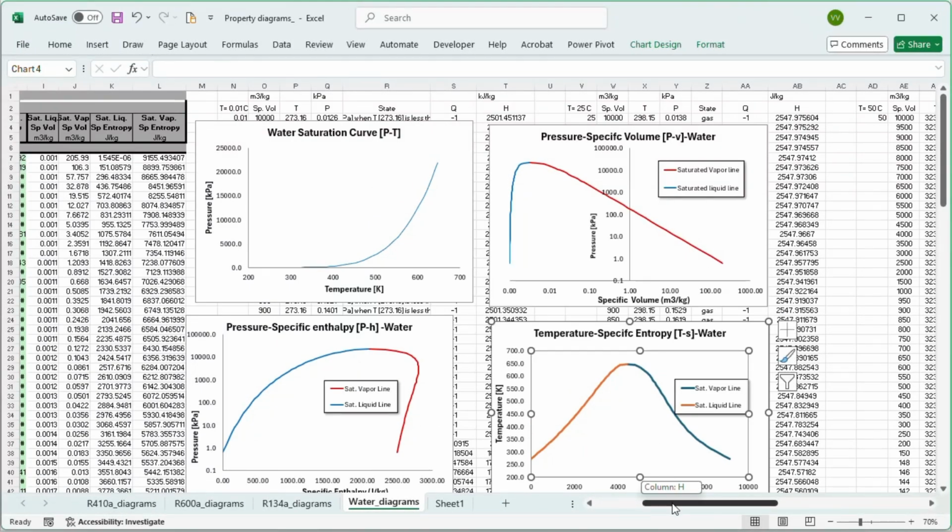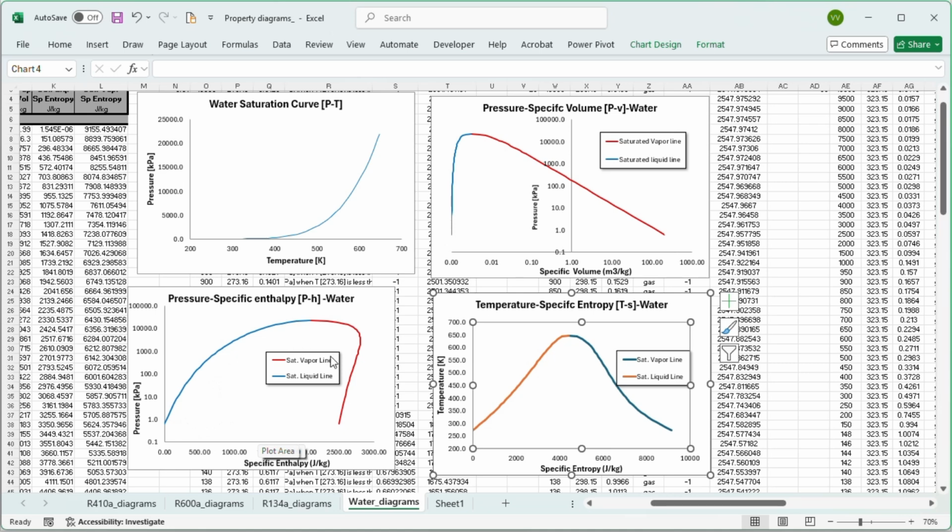Now we already have this pressure versus enthalpy plot. What we don't know is what is the pressure enthalpy relationship for a constant temperature in the two-phase region, and also outside. We know exactly on the saturated vapor and saturated liquid line, but not in the mixture region or in the fully gas region or in the fully liquid region.